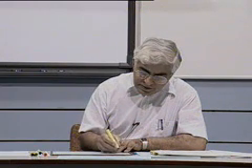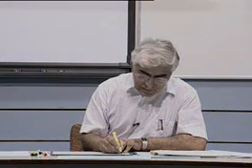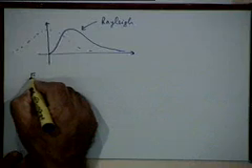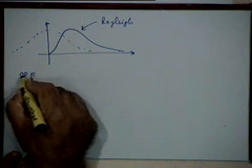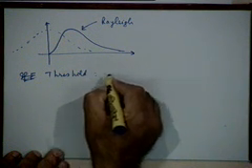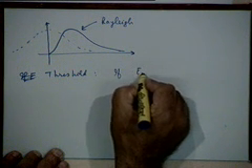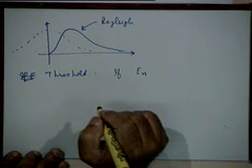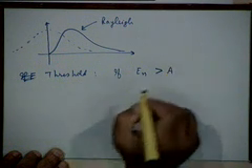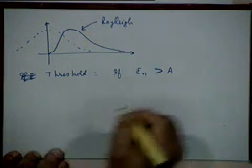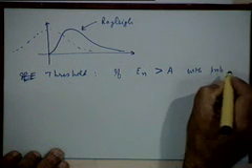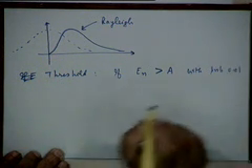Right. So, we have to define the threshold. We will say threshold occurs if E_n, the noise envelope, becomes greater than the carrier amplitude A with a probability of 0.01 or more.